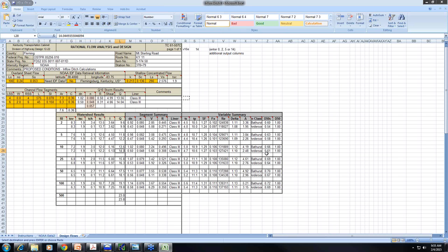As we go on down to the sizing for the riprap, you'll see a minimum D50 is indicated, and it's just over the class 2 lining, so that kicks us up to the recommended class 3 as noted here. The actual calculated shear stress is 4.7 for the 10-year. The permissible is calculated here at 10.6, and these values show the safety factor based on the adjustment of the Shields parameter as outlined in HEC 15.